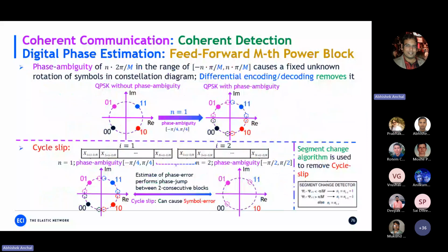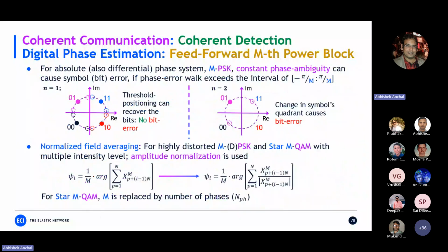I'm not talking about the Acacia DSP; I'm talking about DSP in general. One of the methods they use for highly noisy signals is dividing by the intensity itself. So you temporarily lose the intensity information to get rid of the intensity noise. For highly noisy signals, this is the mechanism they use in DSP, and that's how they try to improve the sensitivity of the receiver.